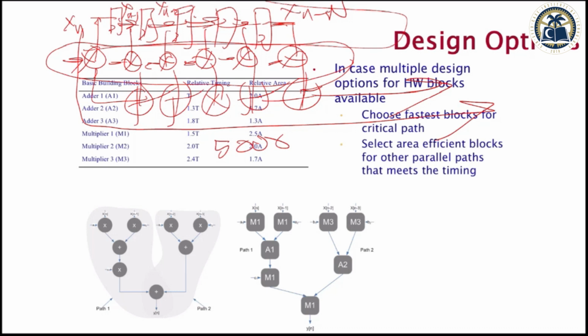And movement is interesting. Why? Because if there is a register and there are now 10 paths, once you move it from this node forward, you are going to get a copy of the register on every path, because an algorithmic register was just delaying this sample which is being fed to 10 different branches. So now you get 10 registers, which are algorithmic registers again. You are not adding any latency. So algorithmic registers are sometimes very, very valuable registers, and we will see the value of these registers, and how you can best utilize them.